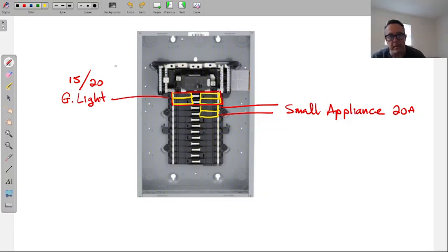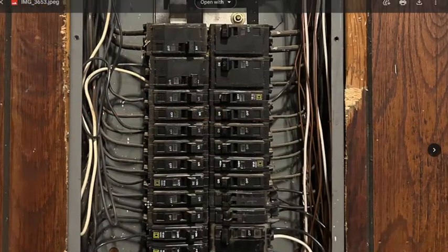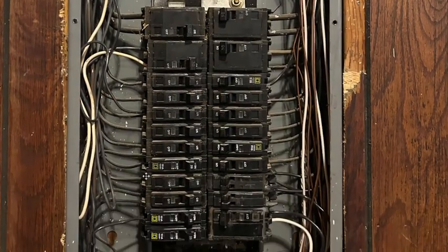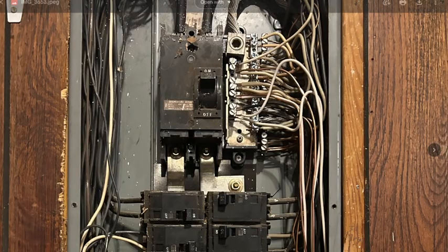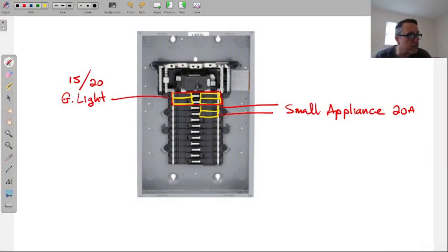So this person asked me to add the car charger to this. So how do you deal with that? First of all, how do I even add another breaker here? And this breaker is a 150 amp main breaker. All right, now I'm not going to get too far into this, but just to set us up. The things that I had to do was measure the amperage that the house was consuming at that moment, or in a few instances, you want to measure at a couple of times during the day as to how the amperage is going.